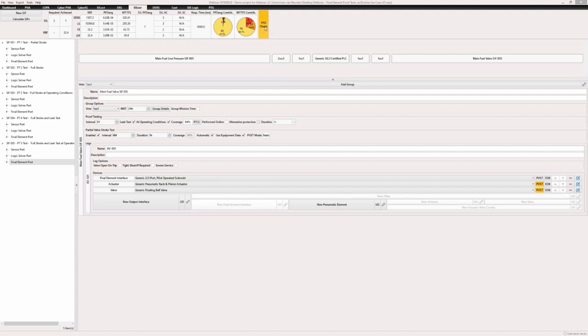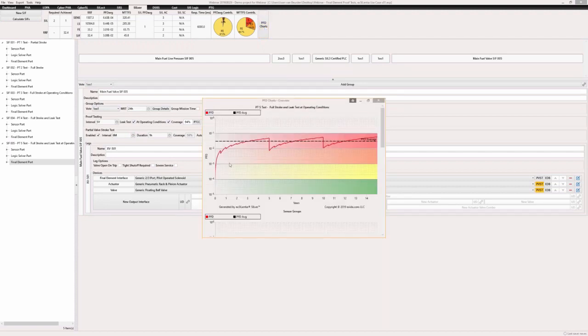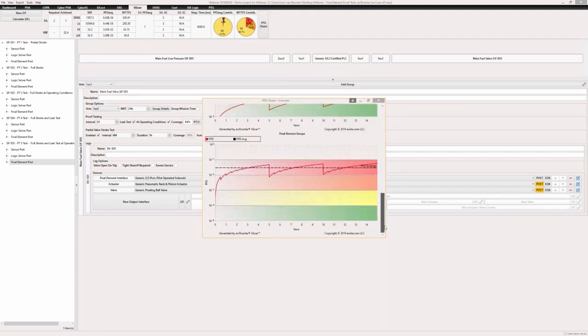So if we run that calculation, you can see specifically, if we go to the final elements here, we see once every 5 years in this example, we do a more rigorous proof test. Once every 6 months, there's a smaller proof test going on. So the simplified equations that I showed on the slide could be updated to add another factor for partial stroke testing. In our case, with our Markov model based calculation engine, it's a discrete time calculation.